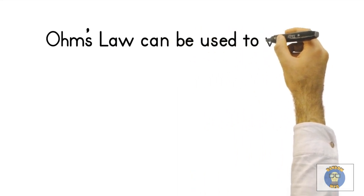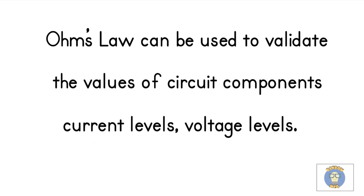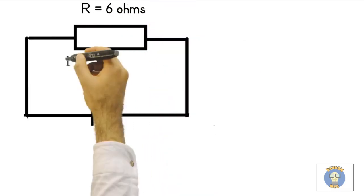What is the use of Ohm's law? Ohm's law can be used to validate the values of circuit components, current levels, and voltage levels. If, for example, an instrument measures a higher current than normal measurement, it could mean that resistance has decreased or that voltage has increased.